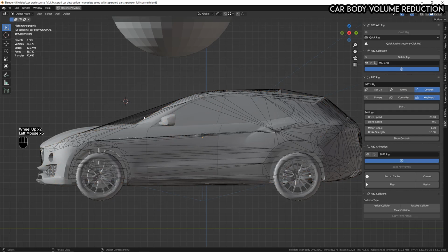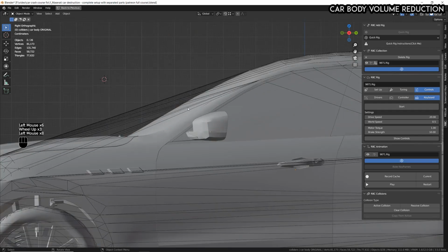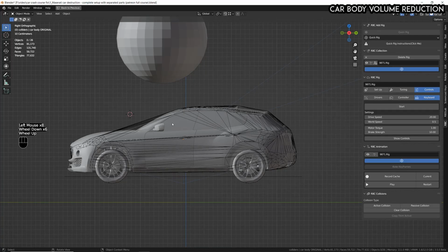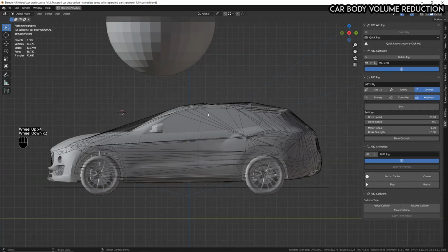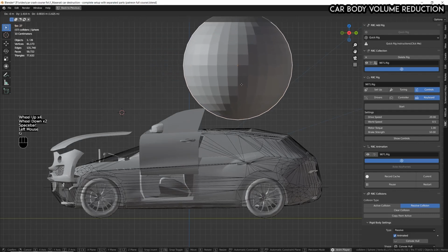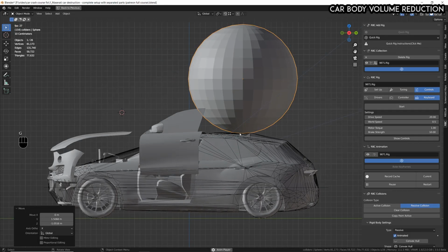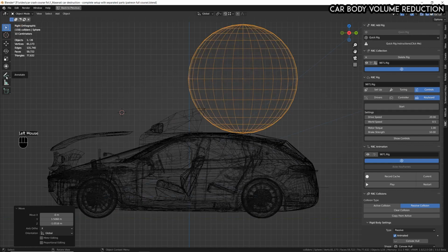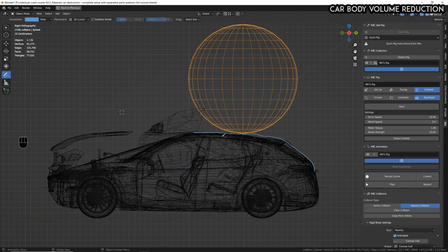For now, this object is not selectable, even if you try to select it. Later, I will show you how to make it selectable. So for now, what I want you to understand is this. If you play the animation, take the sphere, move it, and start to gently touch the car, then interrupt the animation, let's stay in wireframe mode. Basically, right now, the collisions are happening immediately when any collider is close to the car, which can work, but can actually be a lot better if we decrease the size of the rigid body until the collision happens a little bit more inside the car, like here. And I actually want this type of collision to happen all around the car, not only on the top.